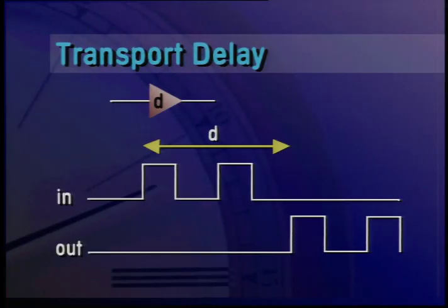Another aspect of the HDL which affects simulation efficiency is scheduling. There are several delay models: transport delay and inertial delay. HDL simulators have typically used an inertial delay model because it's pretty close to what physically happens with individual gates, and it is particularly easy to implement. Here we see the difference between a transport delay and an inertial delay model. Notice that a pulse on the input in the transport delay model makes it through to the output even though the pulse is shorter than the gate delay. In fact, more than one pulse can be propagated through the gate using transport delay.